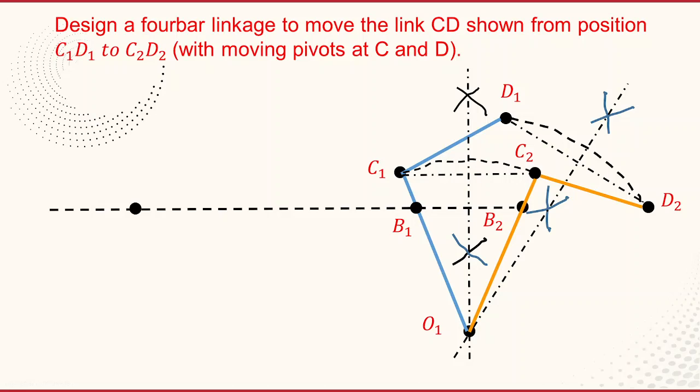Now you can draw the crank radius. The crank radius you can take by bisecting B1 B2. That line itself bisects B1 B2, and we mark the intersection point as O. Now take B1O or OB2 as the radius and O2 as the center, and draw the circle. Here O2A2 is equal to B1O or OB2. This circle acts as the crank.